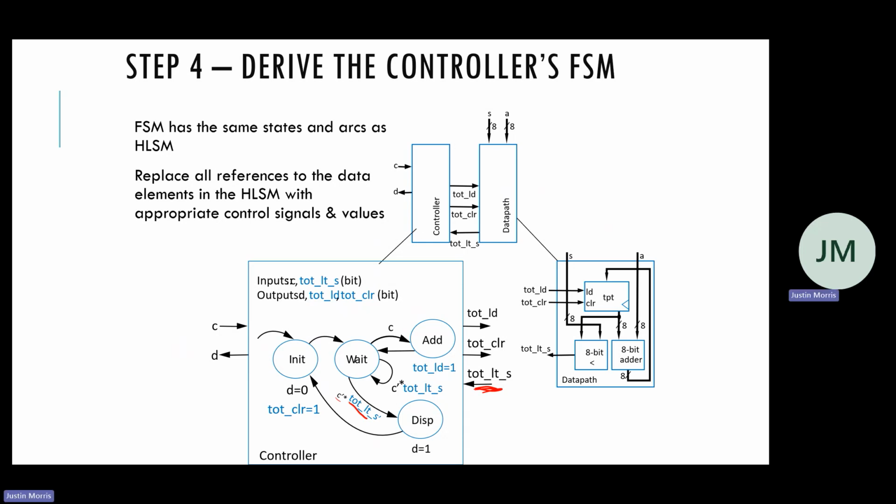And then we also have the same convention as before. If we have a transition with no conditions, we always transition. And if a combination is not shown, you just stay in that state, right? So that is our finite state machine.